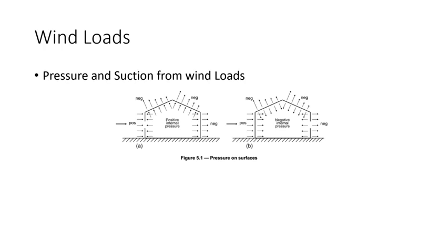But this tunnel test you have to do for such structures which are high rise, and sometimes you even need to study a whole city, how the wind is going to affect that. So in terms of area and in terms of height, it is not just limited to a single structure. When you are studying a whole area, and also due to the height of high rise structures, the wind tunnel test will be used to understand the wind loading.